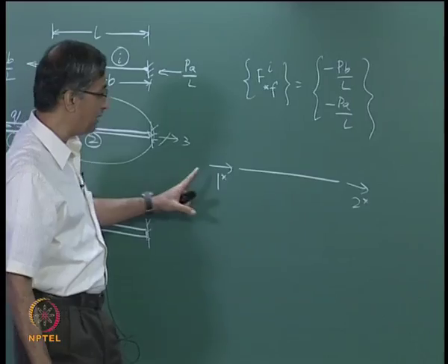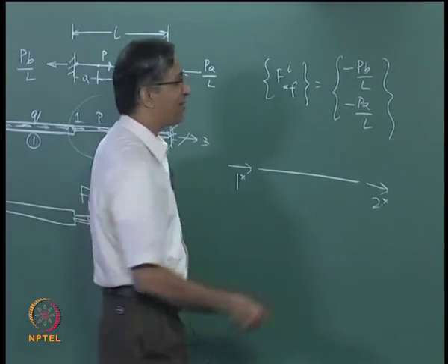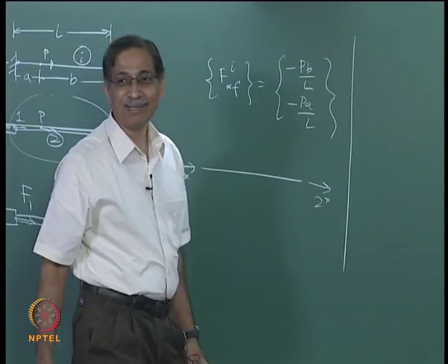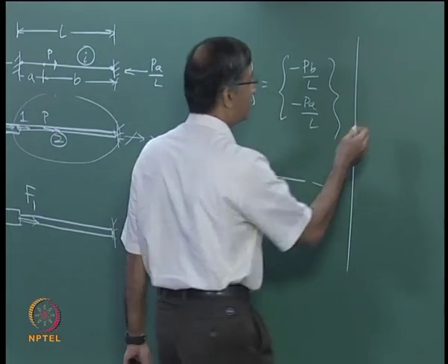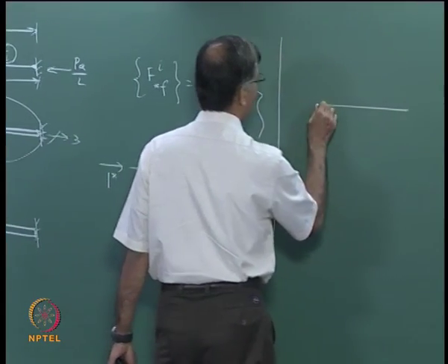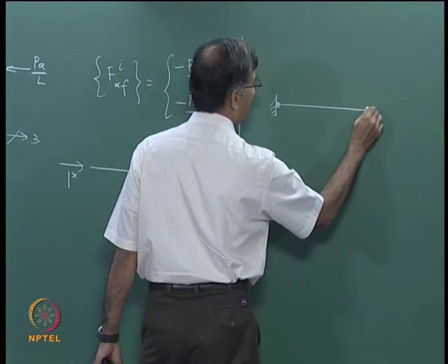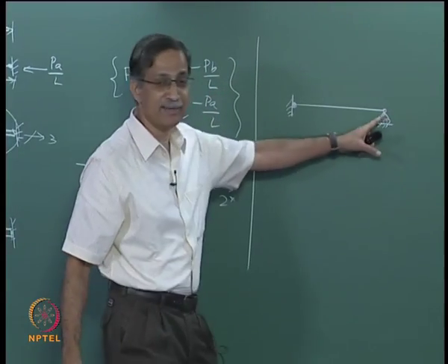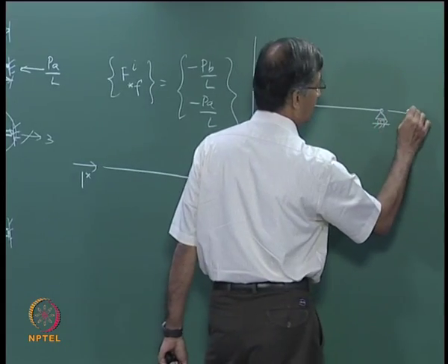You could accommodate 2 different values here. But now we have a problem, because unfortunately, in the reduced element stiffness method we have only 1 degree of freedom, and so our element is like this. We say we arrest this, this is pinned, and maybe you can, since you were uncomfortable in the last class not having a support there, put a support there, right, and this is 1 star.